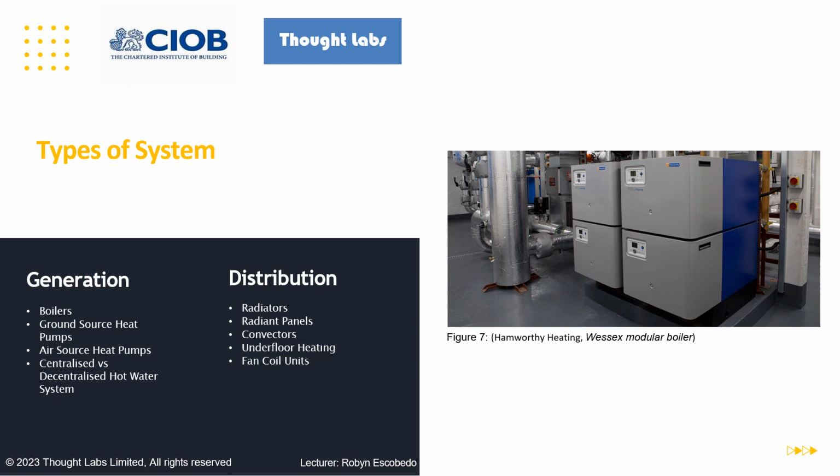This does come with a caveat. If there is a building that has a high hot water demand, for example a leisure centre where there may be 5 or 10 showers running at once, then even a combi boiler is unlikely to instantaneously provide the hot water demand. Therefore, a hot water tank would still be required.